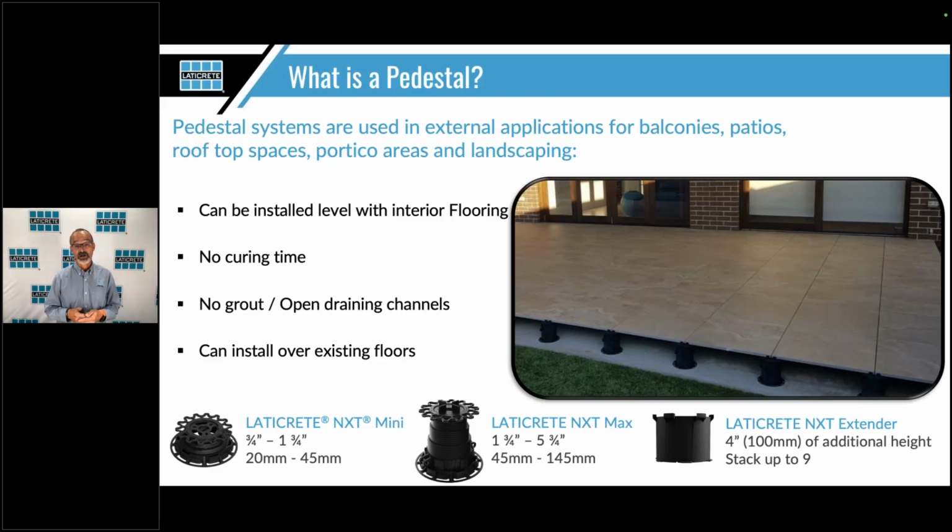I used to be a concrete contractor, and we could only pour so far because if you ever had to repair the door or take the sliding glass door out, you couldn't bury the threshold. These you could actually take it up as high as you want to because you could remove the panels if you ever had to. Along with that, if you're doing tile work, I know we're a tile company and we sell setting materials, but if you're doing a pedestal system on an existing pad right now, you'd be able to finish in a day. You don't have cure times, you don't have to do any grouts, you don't have to worry about any of that.